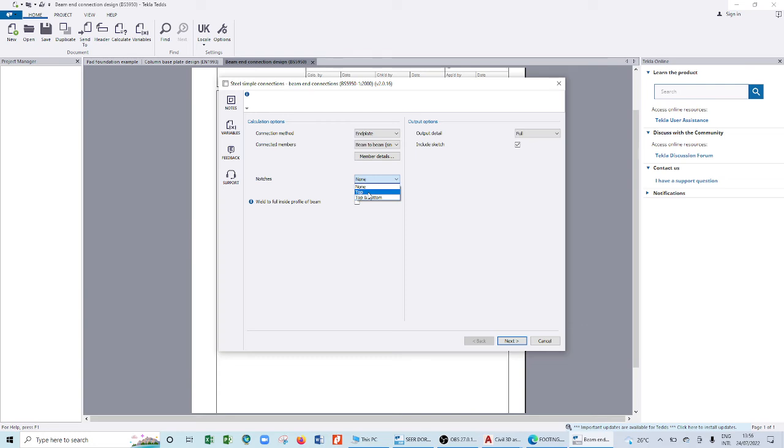And the beam, when you look at what you have, they are the same size. Meaning, if you try to connect them, if they are the same size, and make this hard and push it in, you cannot. So what you have to do is come with this part like this, then you bring it in, then bring it back to this, then bring it in, and then connect it. Now, that distance from here up to here is what I call a leaf notch.